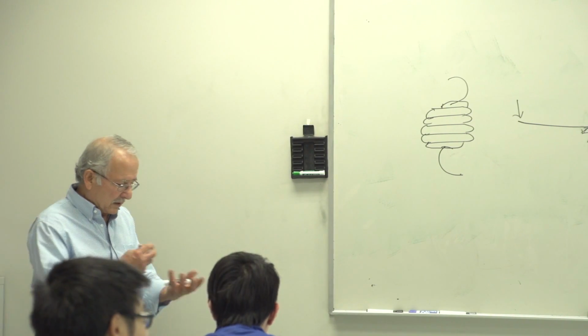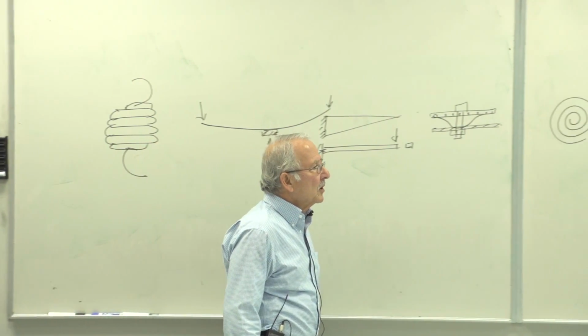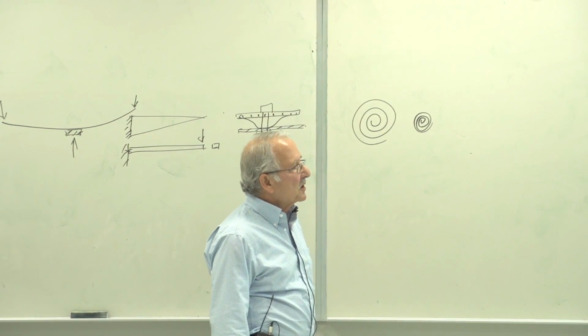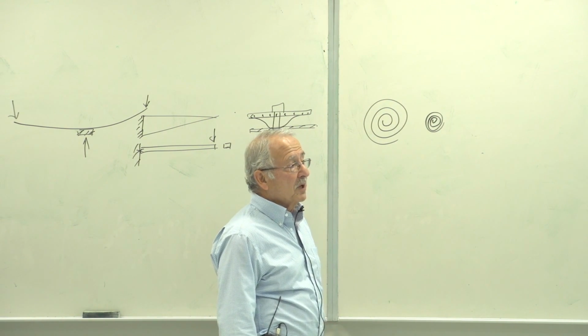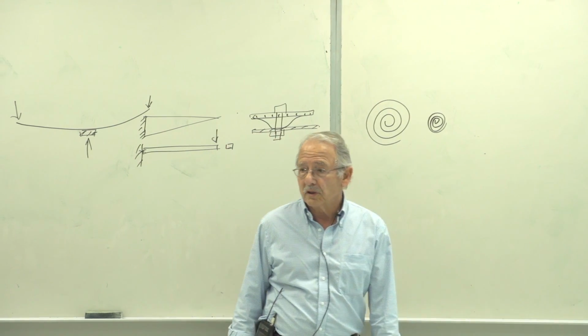Once you do that and you set the spring, in other words, plastically deform it around the mandrel, it takes this shape and more or less keeps that shape until such time that you may apply a very large compressive force to yield it.